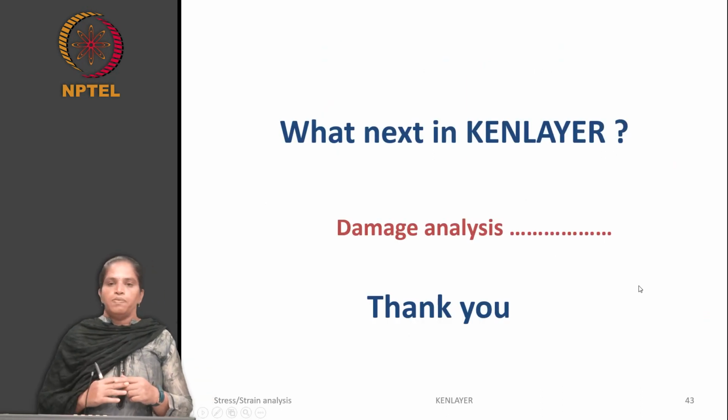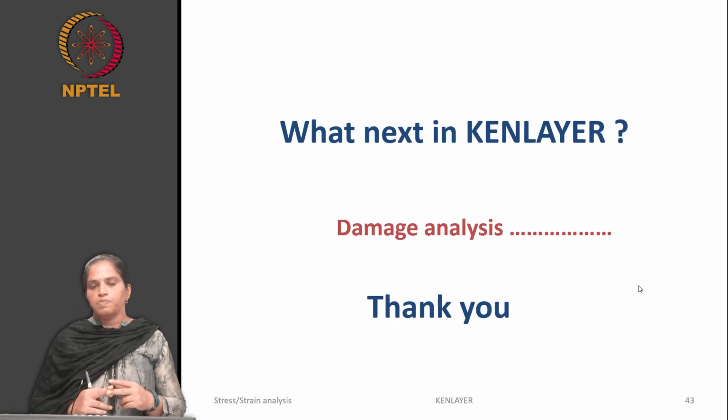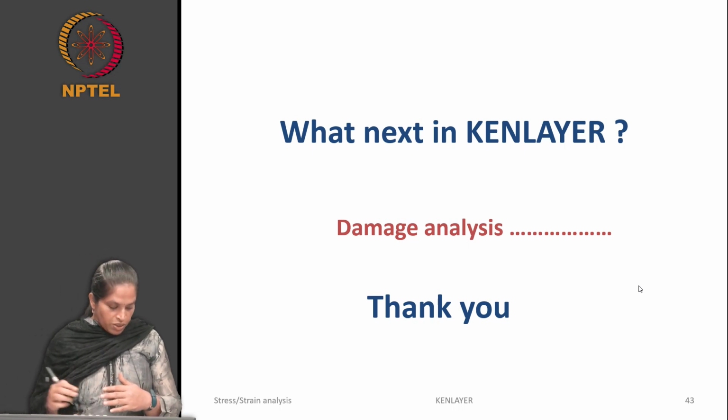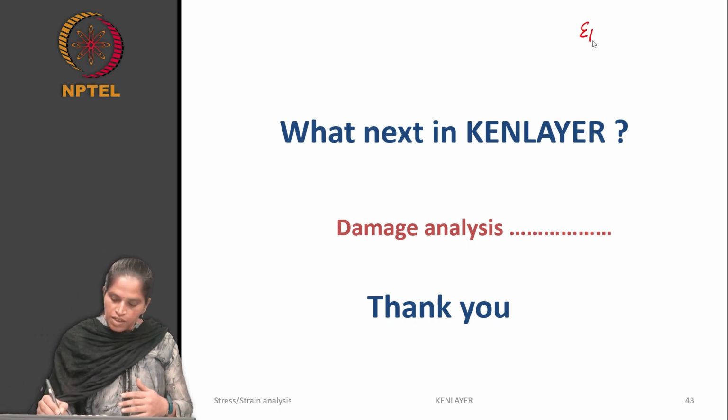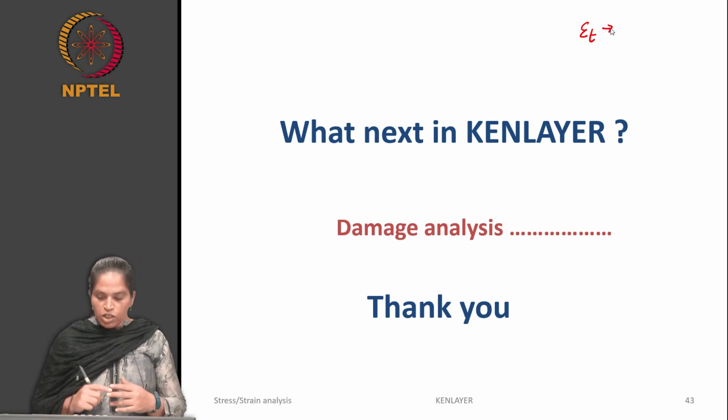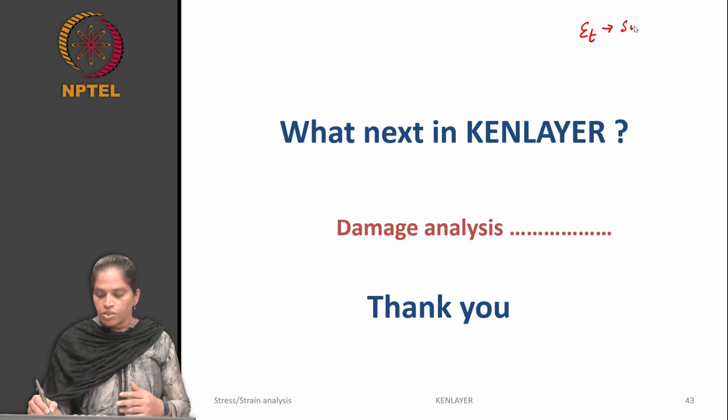So, we have learned 2-layer system and 3-layer system analysis, and we saw what the critical stresses are and how factors like axle configuration, thickness of a layer and modulus of a layer influence the critical stresses. Just to consolidate in short, we saw that epsilon T, which is the critical tensile strain at the bottom of an asphalt layer, is much influenced by surface layer thickness and surface layer modulus.